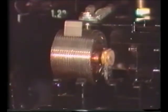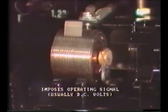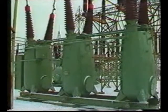However, with an intolerable fault level, the relay output will impose an operating signal on a control circuit, usually in terms of DC volts. This tripping signal is then fed to one or more circuit breakers to cause them to open so as to isolate the faulty circuit. What is the purpose of the circuit breaker?